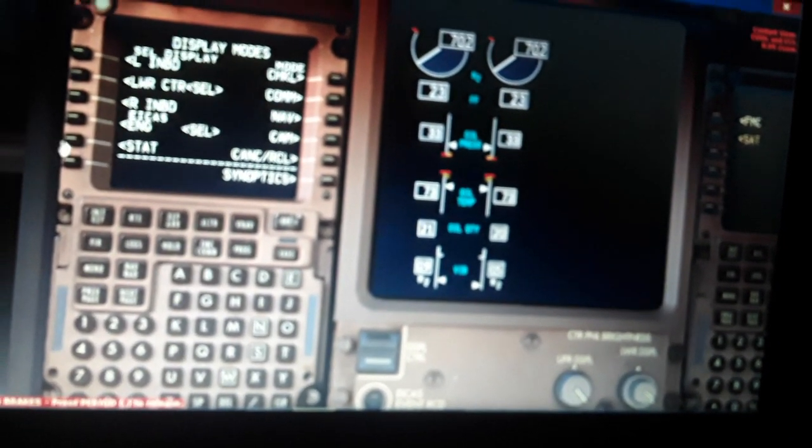So we have the display on. You will see the engine, the status, you can see the hydraulic source, the APU running, and the oxygen level, the checklist, normal menu or non-normal if we have a failure of a system, the communication, synoptics. You can see the doors are closed and the cabin can be pressurized, the landing gear.